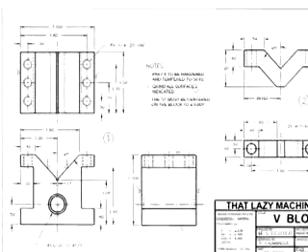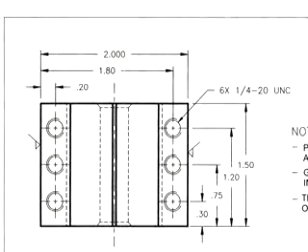Now, you don't want to end up with a jumble of lines that just confuses the drawing even more. So your dimension lines should be stepped or positioned in a way to avoid overlapping lines. And whenever possible, your dimension lines should be cut and the dimensions affixed somewhere close to the midpoint of the line. But as we can see here, sometimes there just isn't enough room for symmetry. So if it has to be off center, well, that's okay.